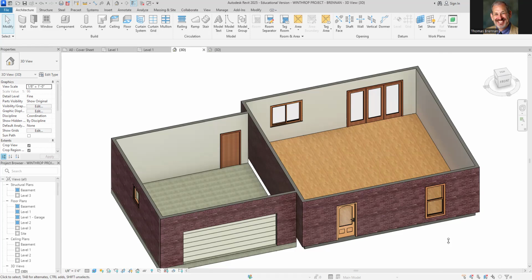So I'm just going to build very methodically. And again, use the construction documents to get that right. Don't forget to make the garage walls negative 1 foot along with the doors. Keep on looking at it in 3D to make sure it looks right. And that is what we're going to do for right now.